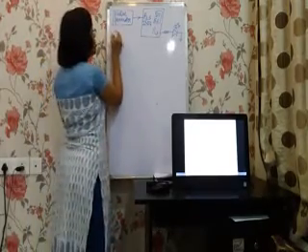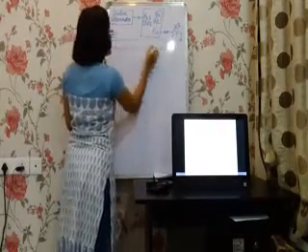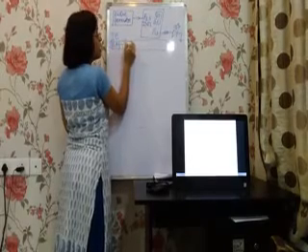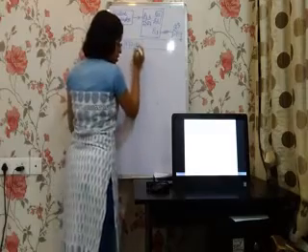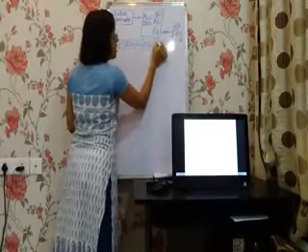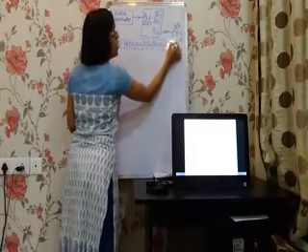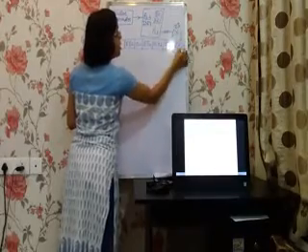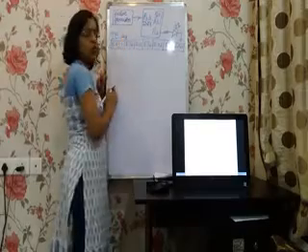Let me draw the format of the IE register, the interrupt enable register, which we had seen already yesterday: enable all, nothing over here, enable timer 2, enable serial communication interrupt, then enable timer 1, enable external interrupt 1, enable timer 0 and enable external interrupt 0. This is the format of the IE register.